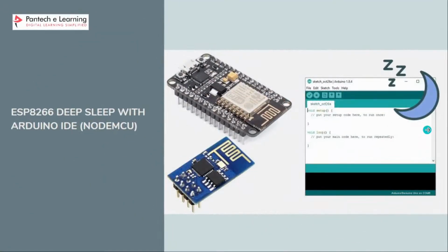So the next topic is deep sleep. Now we are going to learn how to use deep sleep with the ESP8266 using Arduino IDE. Here we will cover deep sleep with timer wake up and deep sleep with external wake up using the reset pin.